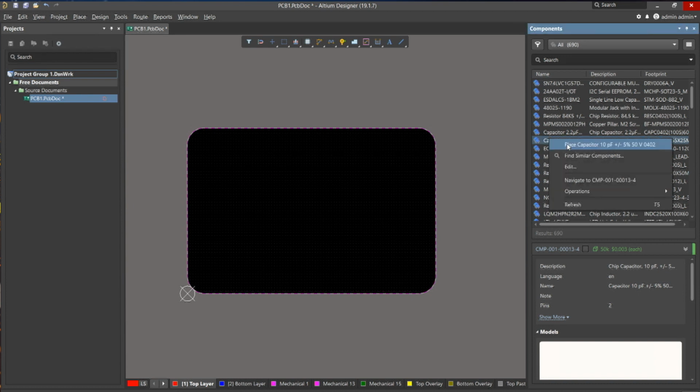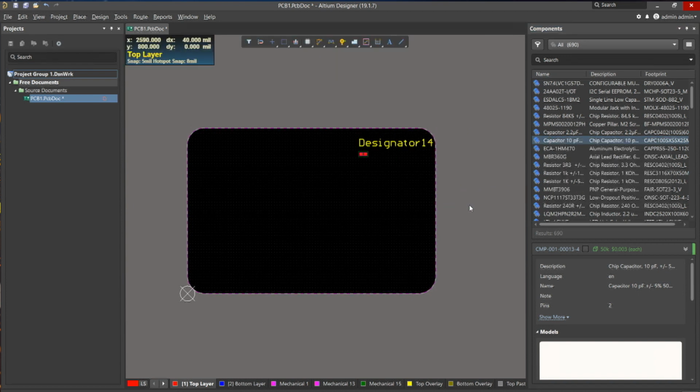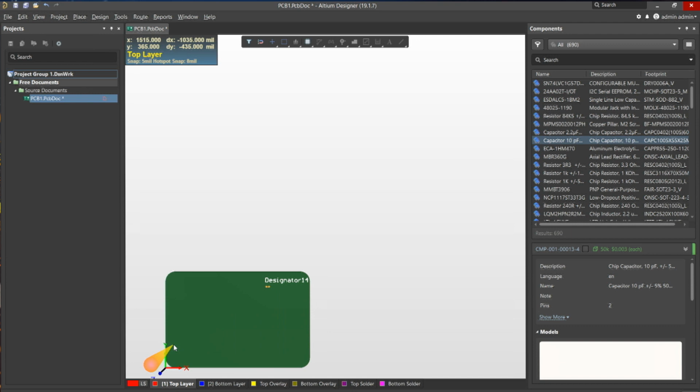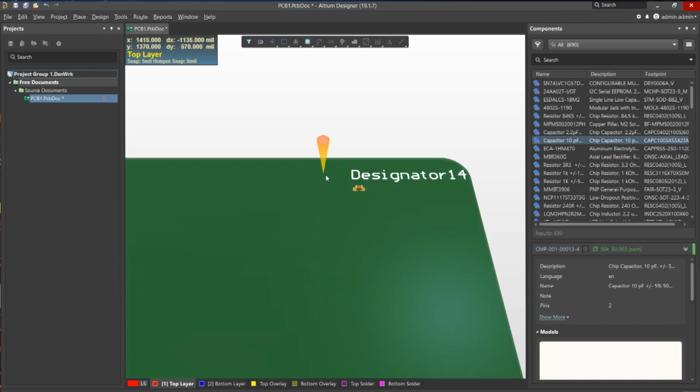Let's place this capacitor. All right, now we're working with something a little bit more realistic, we'll put it that way, right? So once again, that DXF import is probably one of the most common things that we see as far as getting that board shape from our mechanical designer. From the ECAD side of things, my personal preference is that I don't like doing things twice.